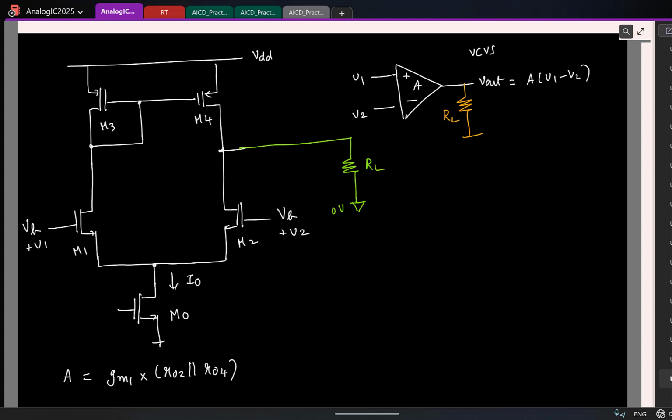Yeah, the problem is operating point current. I mean, this resistor will draw some operating point current, so you don't want DC currents to flow. So instead, how do you connect it now? Yeah, that is one way in which we do. We put a large capacitor so that, as we know, in steady state, DC current through the capacitor is how much? 0. So no DC current flows, so DC voltage is 0.